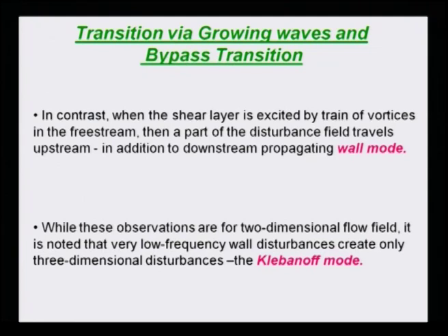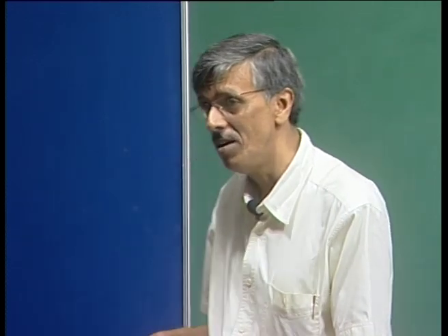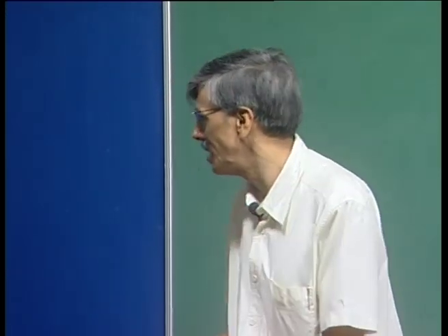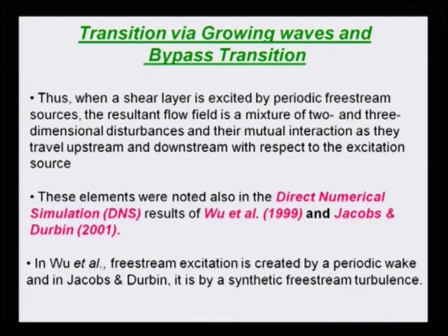Okay. We also noted very clearly that if we create a disturbance even inside the shear layer but at very low frequency, then we do not create any two-dimensional disturbance field. Instead, we create a three-dimensional disturbance field which we call the breathing mode or the Klebanoff mode, right? So this is basically a quick summary of what we have been talking about.